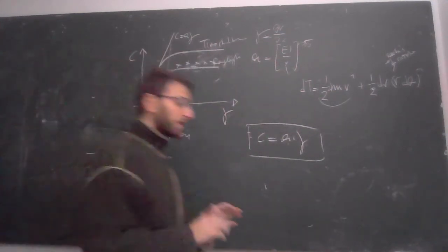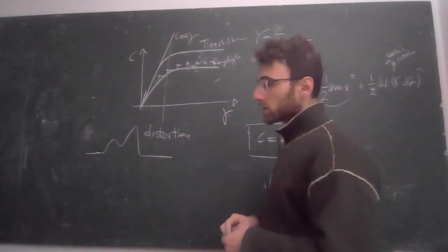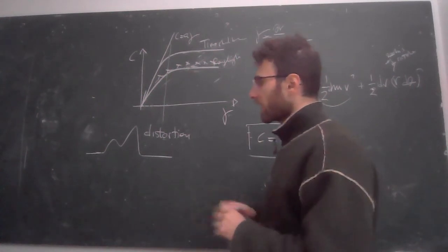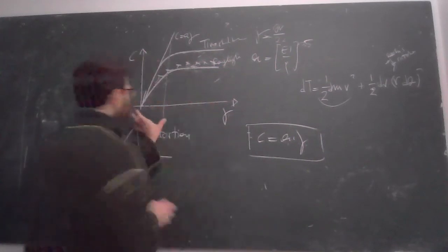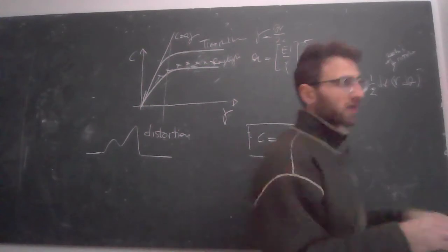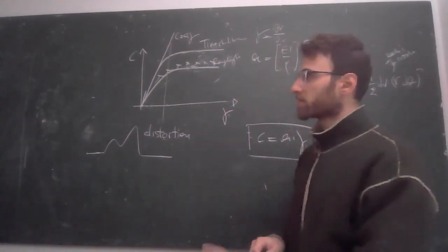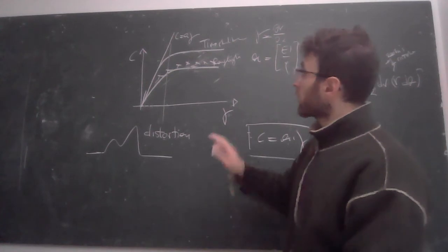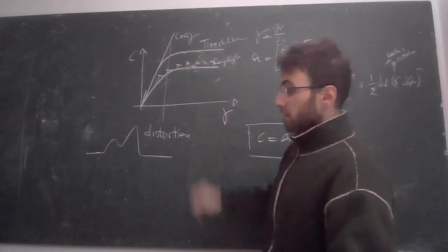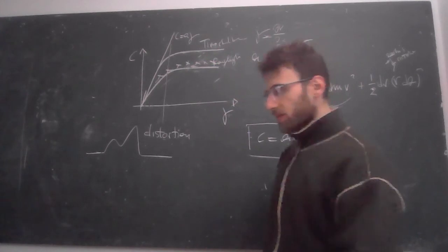The beam is a highly dispersive medium. Euler-Bernoulli tries to grasp the dispersive behavior when we are dealing with low wave numbers. But when we go to higher frequency waves, the Euler-Bernoulli hypothesis does not stand, and we must model the beam using the Timoshenko and the Rayleigh beam. Okay, I hope it is clear.